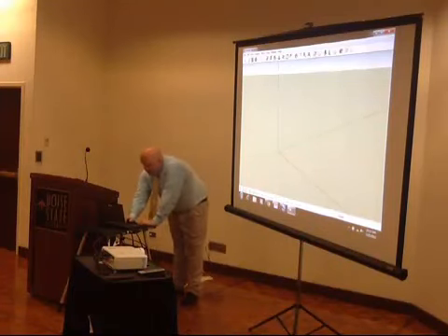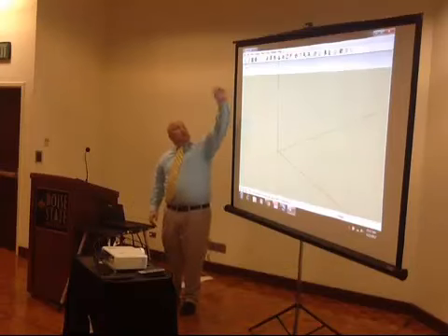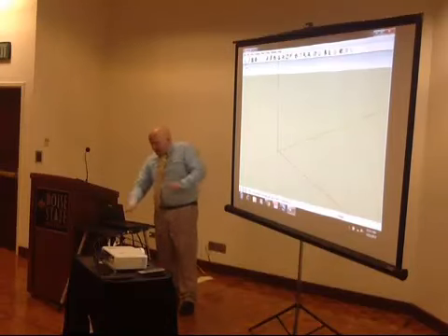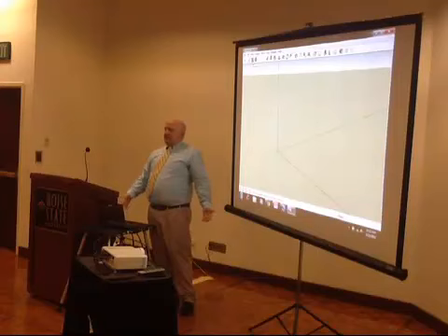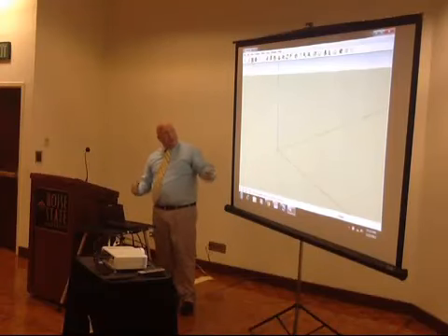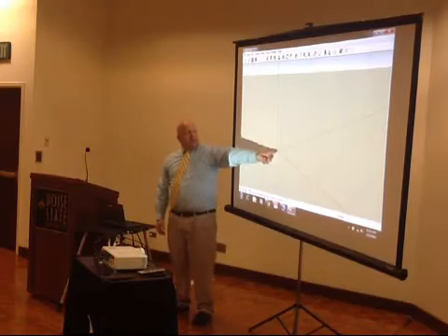Let's start with the very basics of SketchUp. Your tools are across the top. Your select tool is going to be your most common one as we're moving around. Your line tool and your rectangle tool are going to end up being the tools that you use most often when building buildings. But let's describe the shape, and then we'll drag a shape into it.